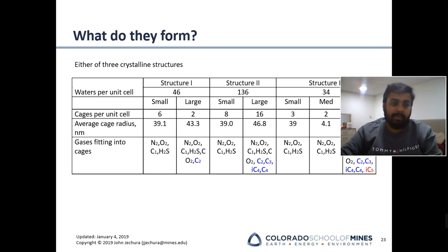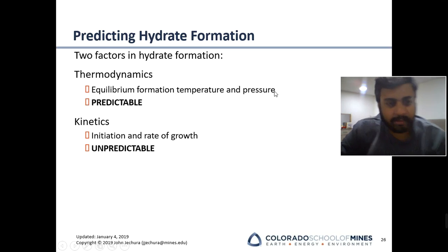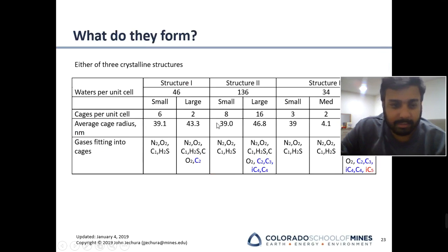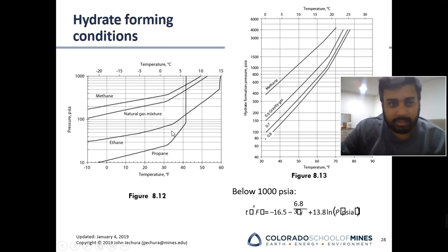Well, what are the main prerequisites for hydrates? The main things needed for hydrate formation are water and temperature. These are the two main things. It has to be a temperature and pressure equilibrium. But we don't know, once it is formed, how much there can be. For example, here you can see that it just blocked all the pipelines. See, whatever oil or gas you want to flow through this pipe, all is made of this solid hydrate, so we cannot do anything with it. So it's quite unpredictable, and that's our job, to predict this hydrate formation.